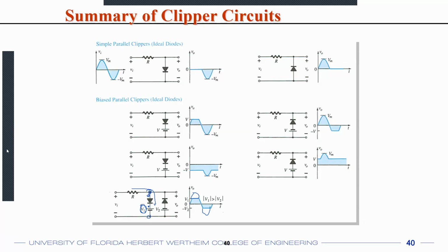If the input voltage is less than V1, in that case, you will have the diode reverse biased, and the voltage drop across the diode will be the same as the input voltage, which you see between these two terminals. So when the input voltage is less than V1 but more than 0, then this part is activated, and you see the voltage across the diode and the battery structure as what you see on the right side.